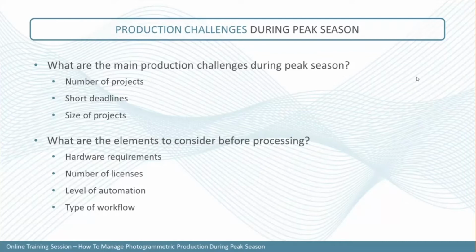Finally, one of the last things we'll talk about is the level of automation you want to have for your photogrammetric projects. There are basically three main options that we offer for the processing: the graphical user interface, you can also use a script with the automated workflow, and you can also use a script and run it within the command line by calling Correlator 3D.